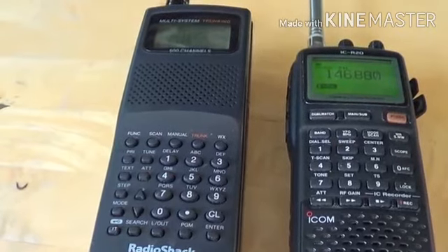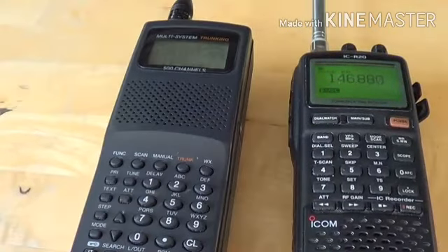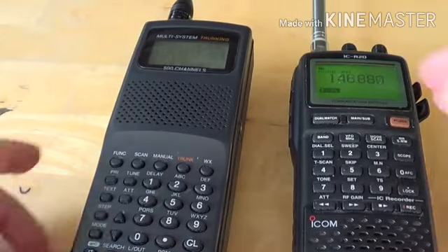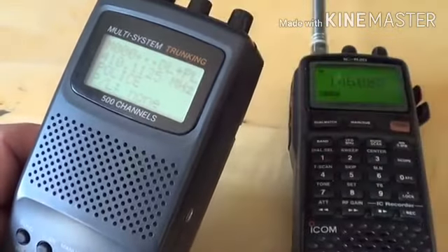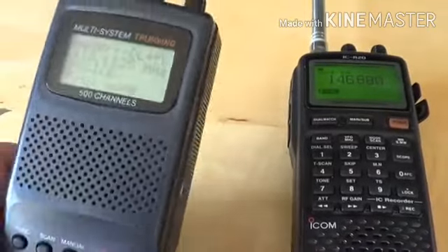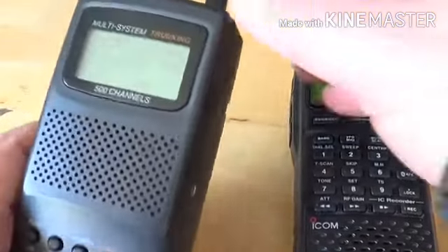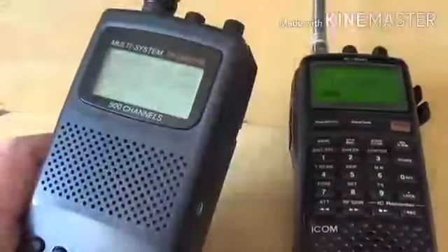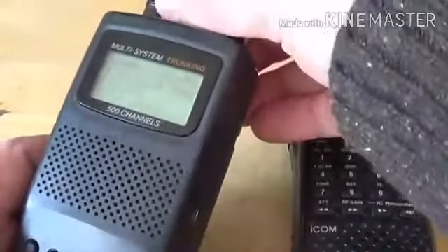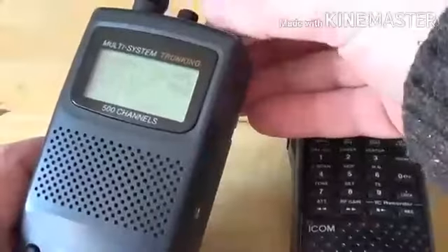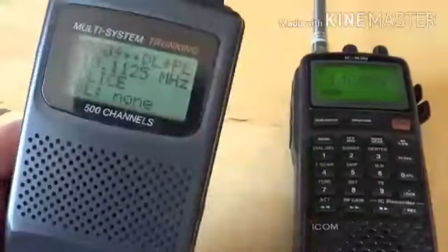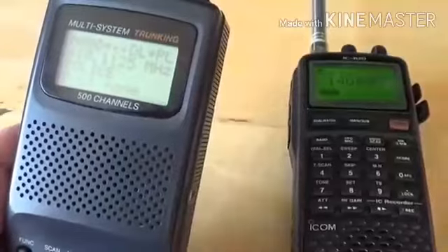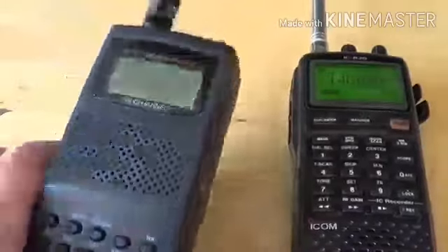And today we're going to talk a little bit about squelch. The reason why we have squelch is multiple. First of all, in a channel where there are lots of communications, what's nice about squelch is that by positioning the squelch at a certain level, it prevents the static from being heard and lets the signals that you want to hear go through. So that's cool, because if it wouldn't be there, then we'd have this static all the time in between conversations. That's kind of annoying. So squelch is there for that, first of all.